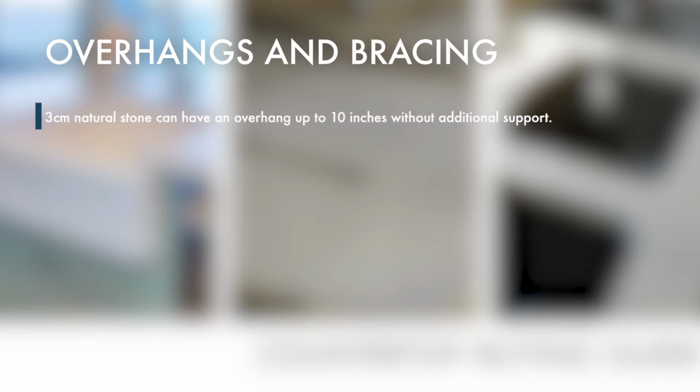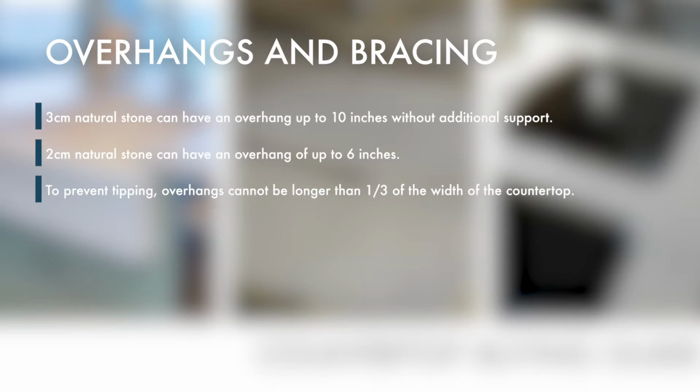Overhangs and bracing. 3 centimeter natural stone can have an overhang up to 10 inches without additional support. 2 centimeter natural stone can have an overhang of up to 6 inches. To prevent tipping, overhangs cannot be longer than 1/3 of the width of the countertop.